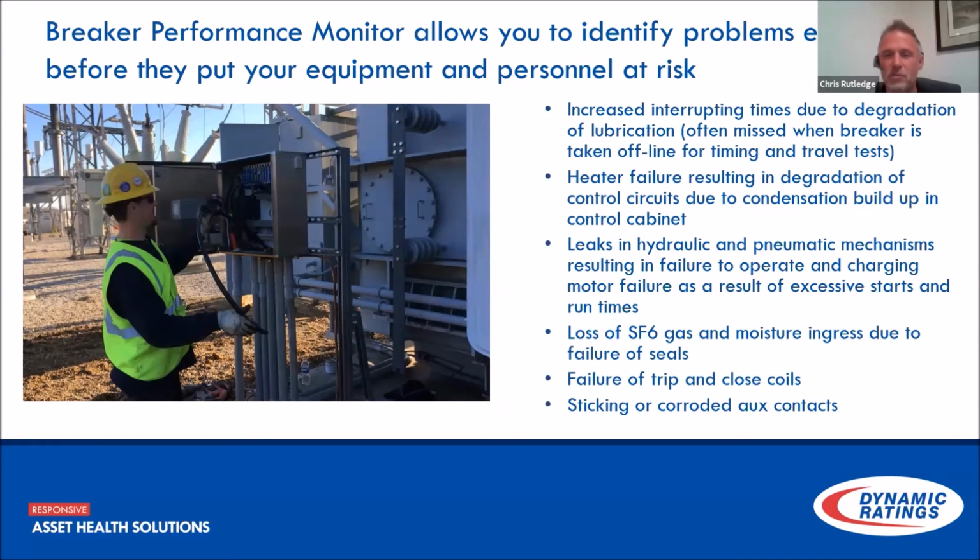Another event that can occur between these inspections and offline tests, and again we're looking at 5 to 8 years as how often this is getting run, so a lot can occur in that period of time, is heater failures. A lot of times this happens between inspections. When it does, I've seen control circuits where they had the actual paper fuses in them that had just fallen apart. So our trip circuit was broken completely, and we have a failure to operate. It's also degradation of your wiring and your electrical components.